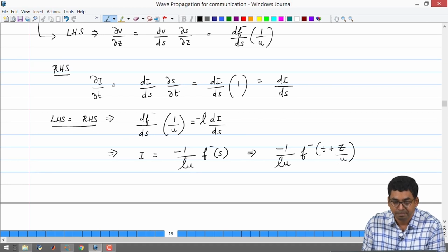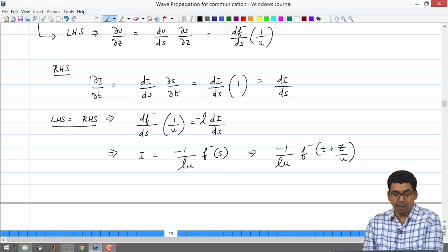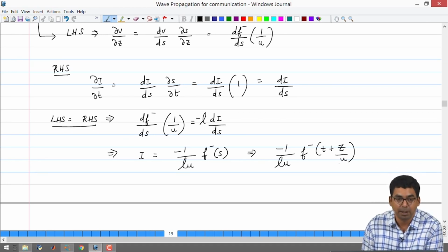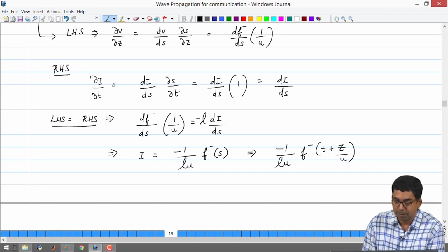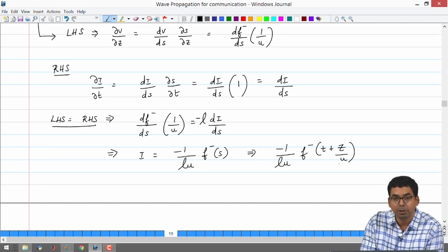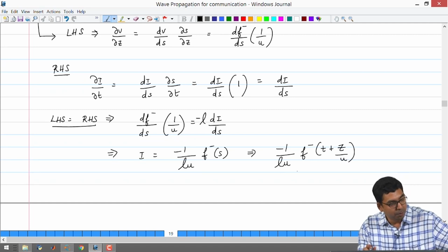Okay. So here it is abundantly clear that if you have a backward travelling voltage wave, the method of calculating current is slightly different. Since we are looking at this equation in the form of Ohm's law, you can say I is equal to V divided by R, but it looks like it will have the unit of characteristic resistance or ohms, but you are going to have minus 1 divided by Rc, or characteristic resistance, multiplied by the voltage, right.